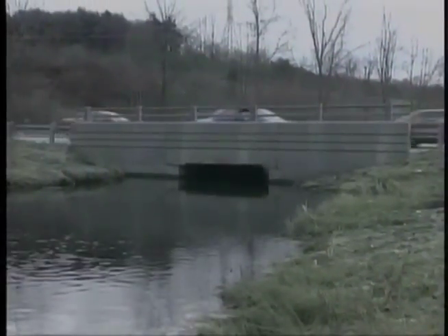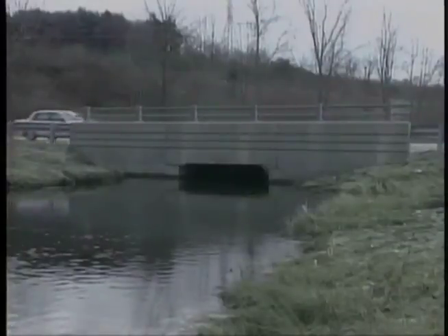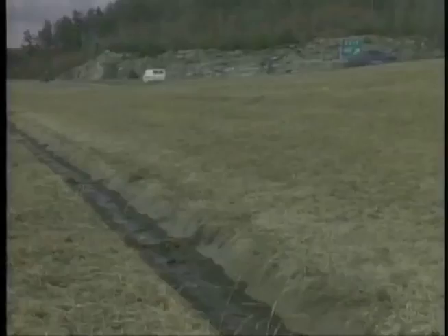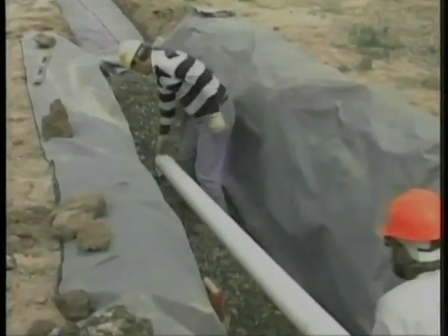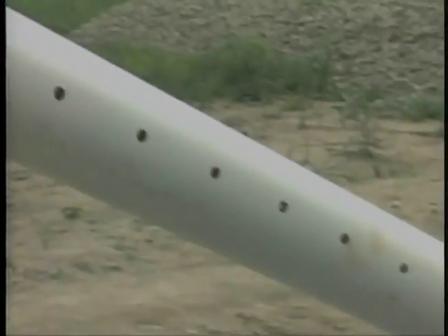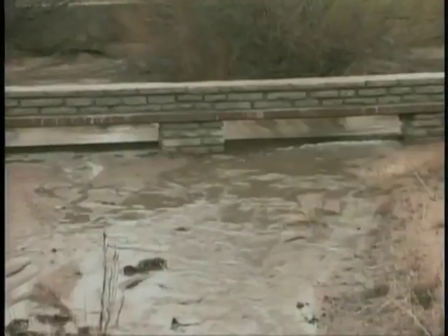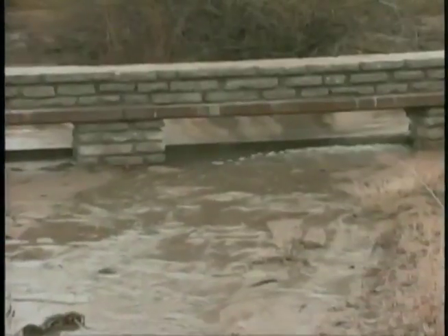Subdrains are designed to extract and control excessive groundwater. They are installed around buildings, along highways, and anywhere subsurface water may cause softening, frost heaves, or erosion. The subdrain system collects water using perforated pipe. The perforations allow groundwater to enter the pipe and follow the flow line into a controlled collection area, a storm drain system, or into the environment.